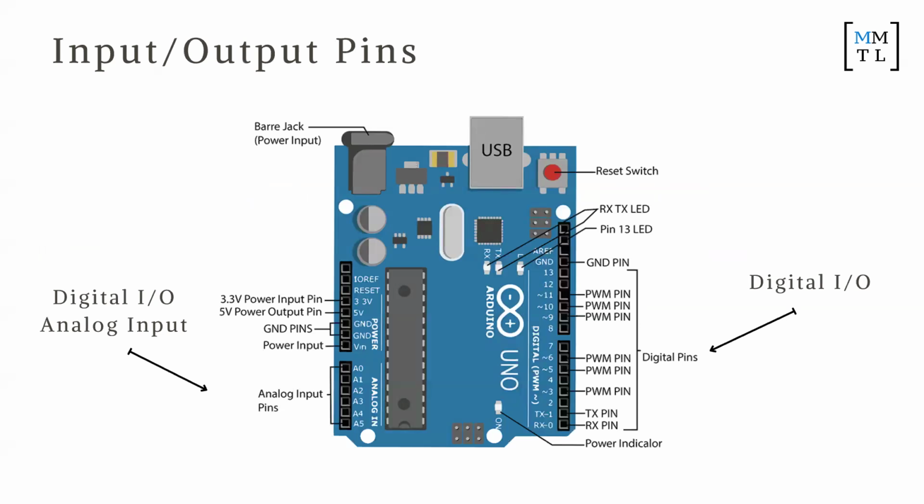So input pins, again, so these are the digital I/O pins, right? And these ones here are capable of digital I/O as well as analog inputs. Does that make sense? And these ones here, PWM, are ones that can write out pulse width modulation signals. Okay, so these can sort of fake write out analog signals here. So these ones here with a tilde are labeled as PWM.